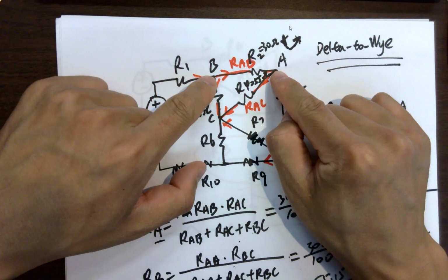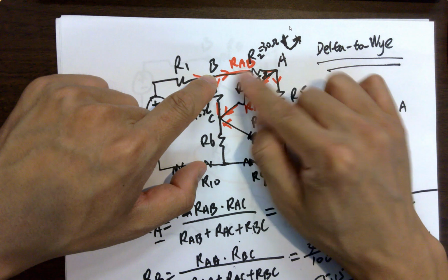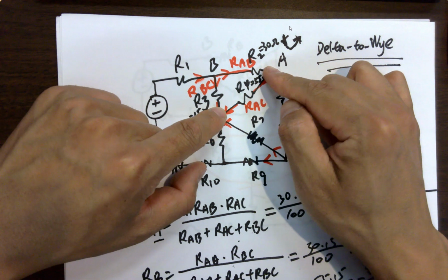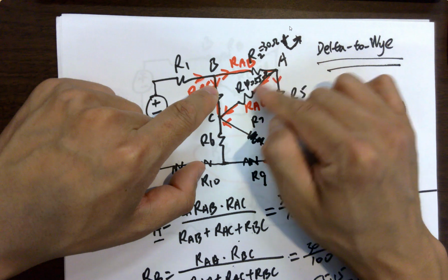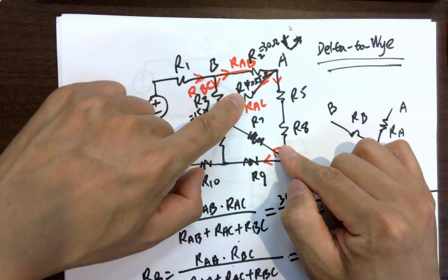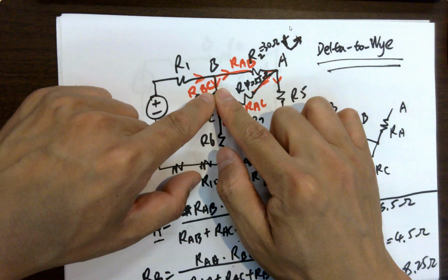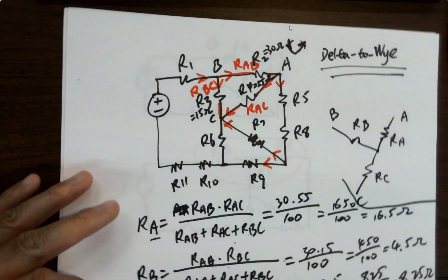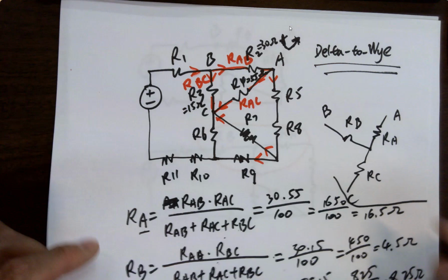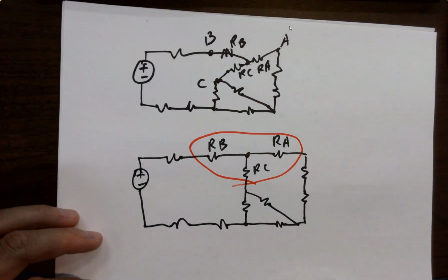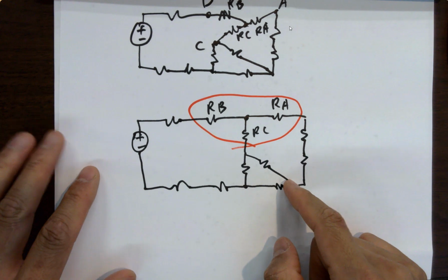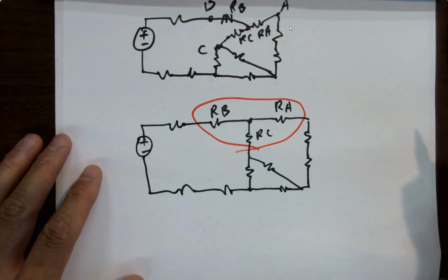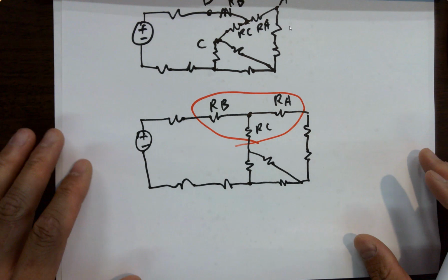Yeah, because after this node, it just couldn't move forward. Split in parallel, you're thinking, hey, we can combine these two resistors as a parallel resistor. Not actually, because you got current split here again, and then this comes back. It's making things complicated. So I have to convert it to the Y shape like this. If we move forward with this circuit, you just follow the same method we just did.